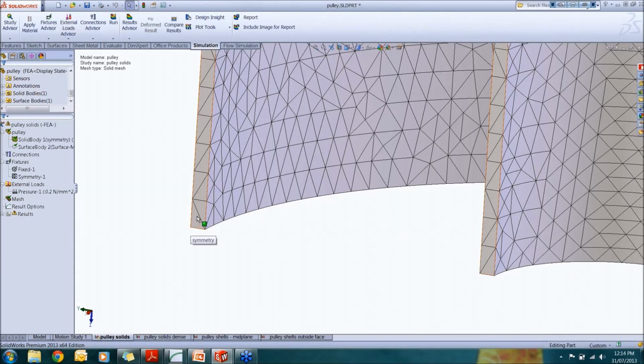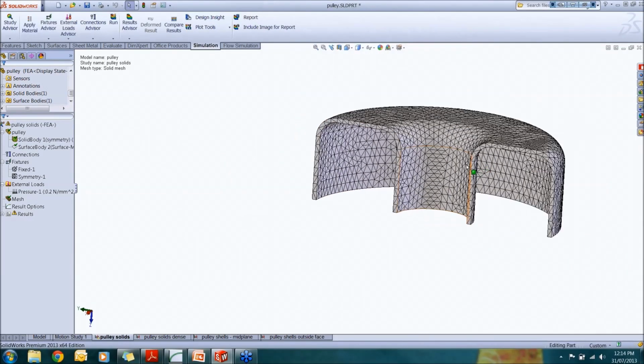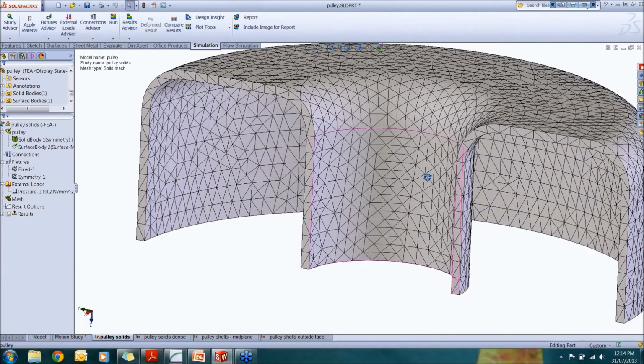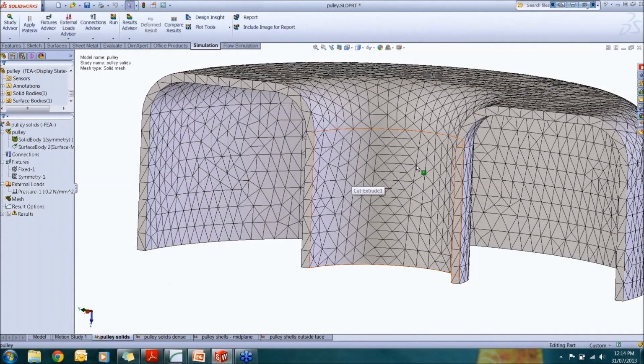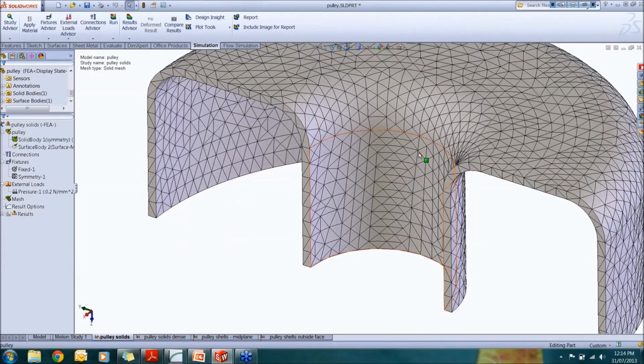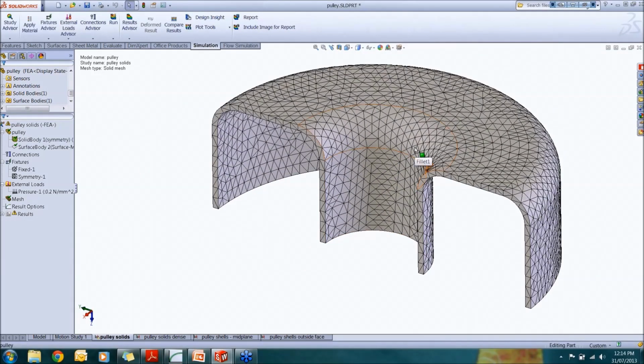Therefore, if there are any significant changes of stress happening through the thickness somewhere in the middle, we are not able to capture it because there is no calculation point for us here. Now, the other important information, as you can see, the connectivity of the mesh is not very great, and it is a very rough estimation of the actual geometry we have.